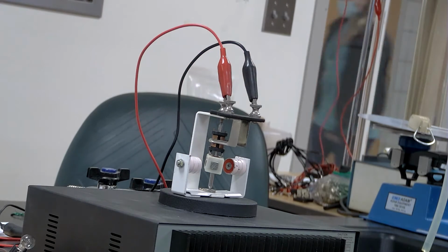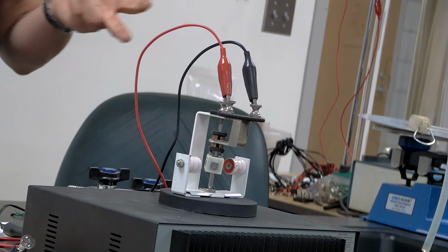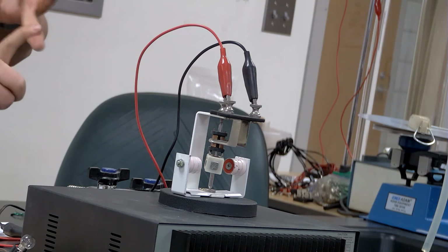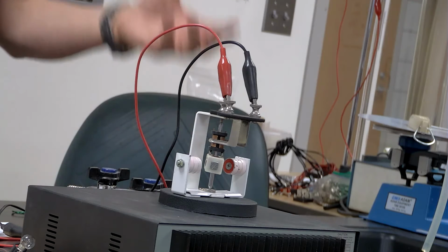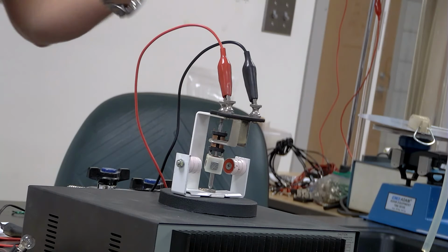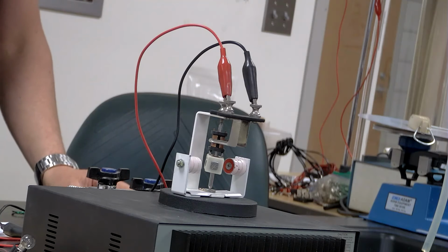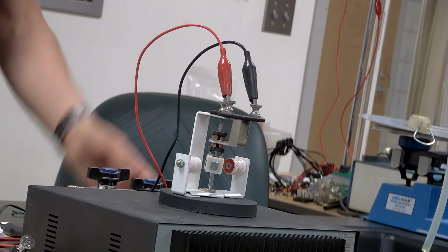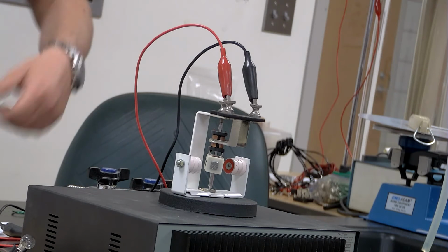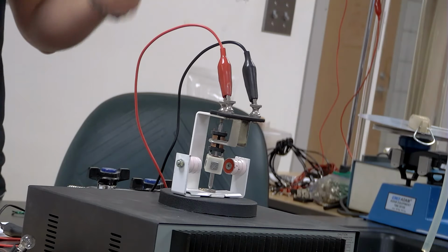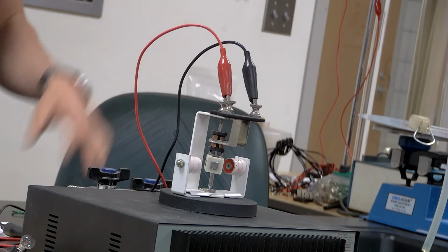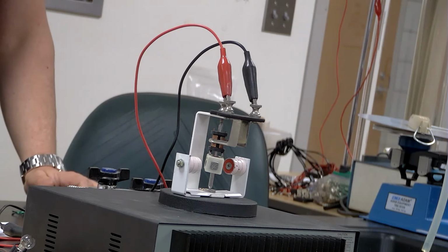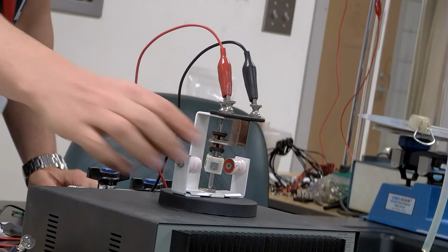Anytime you have a current through a wire, in the presence of a magnetic field, you have the potential for a magnetic force. You can magnify those by having that current generate its own magnetic field, because currents generate magnetic fields. You put a piece of iron within that magnetic field, it aligns the domains within the iron and increases the magnetic field strength. And so you get an even stronger magnetic force, and we can get that motor to do more work, to spin faster. So that's what this one does.